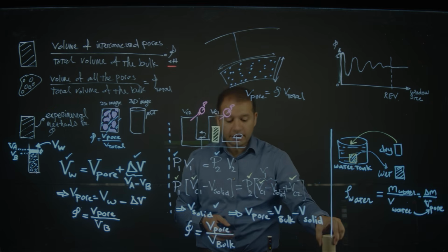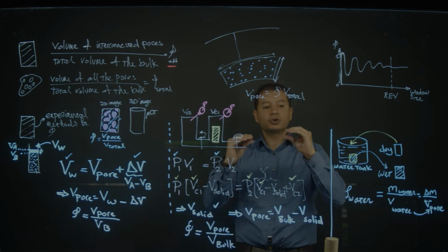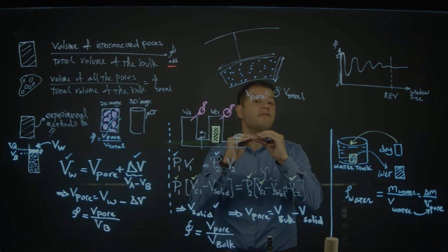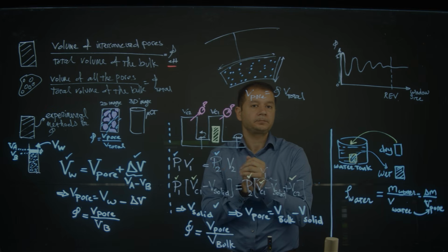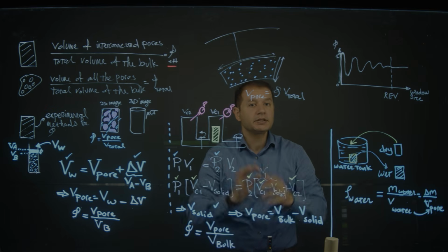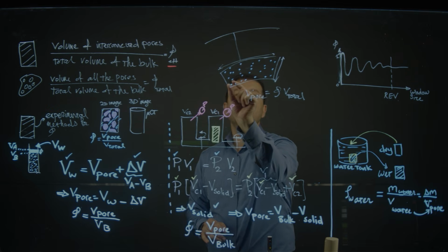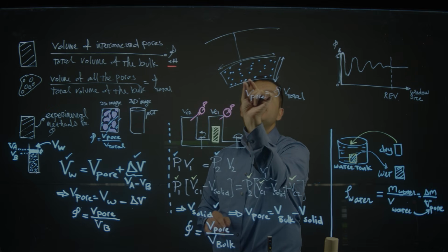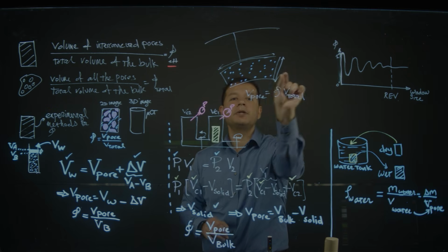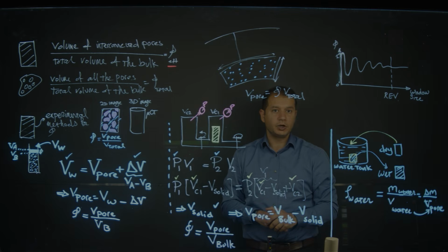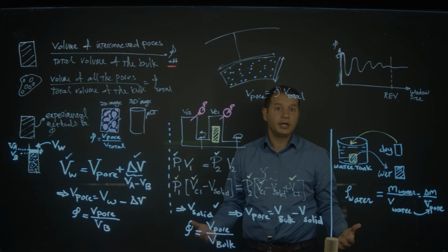You can have very hard rock or shale formations that would have very low porosity. So porosity is very heterogeneous. And so you need to calculate the porosity times the volume of each element, and sum them all up in order to understand the total void volume, or pore volume, you have in your reservoir.